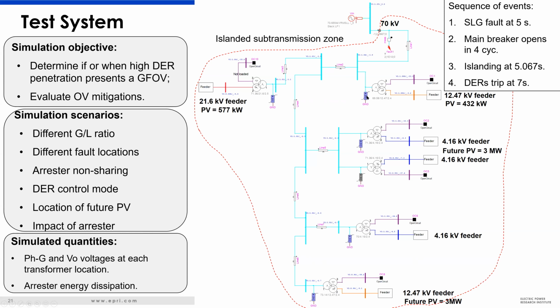During the night when there is no PV, this overvoltage condition can happen, or it could be even worse than this number because in pre-dawn hours the loads are lower, so this overvoltage can increase. With the existing level of PV at 3%, there was no significant change in overvoltage because the PVs are very low.